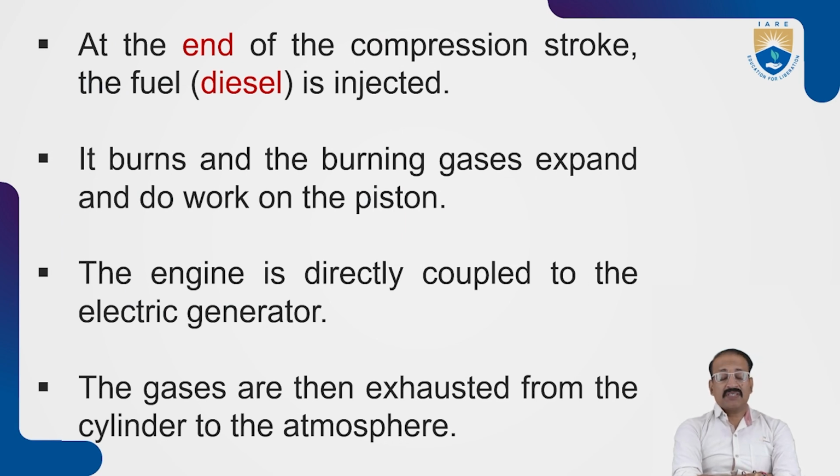At the end of the compression stroke, why do you need to put some pressure? At the end of the compression stroke, the fuel is injected. Without this, the fuel cannot ignite. Due to that, it burns, and the burning gases expand and do work on the piston. So the piston will be moved. Because of this expansion of the burning gases, the engine is directly coupled to the electric generator.